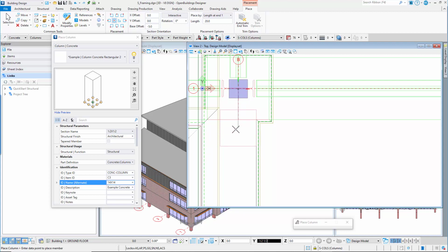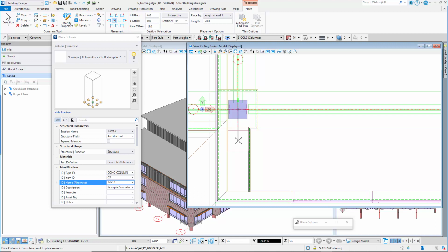This invokes the AccuDraw Set Origin shortcut, meaning the AccuDraw compass is relocated to the snap location. Now move the cursor towards the main entrance and press Enter to lock the AccuDraw axis. Key in the distance of 4 feet or 1200 millimeters to locate the new C3 column 4 feet or 1200 millimeters from the B1 grid location. A data point or left click accepts the location and places the column.